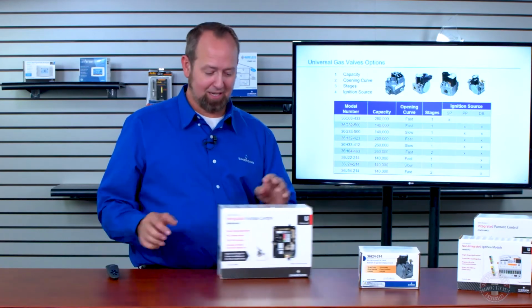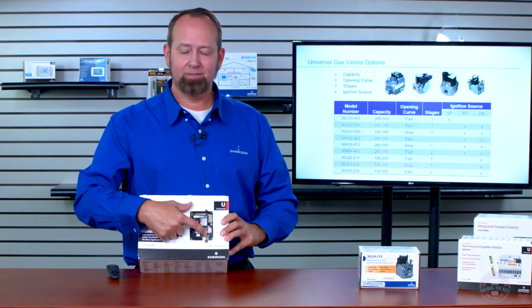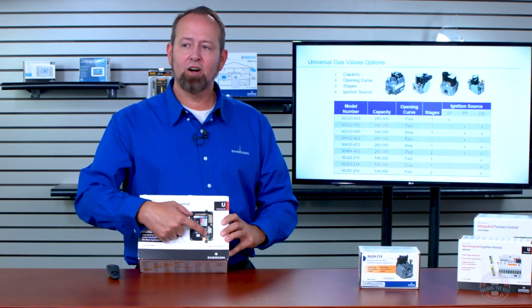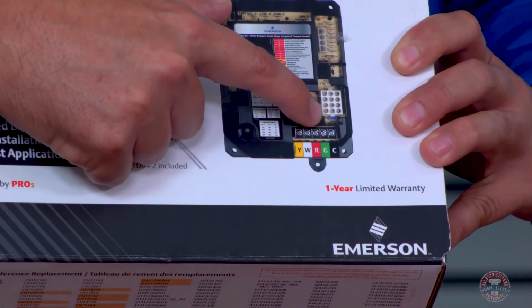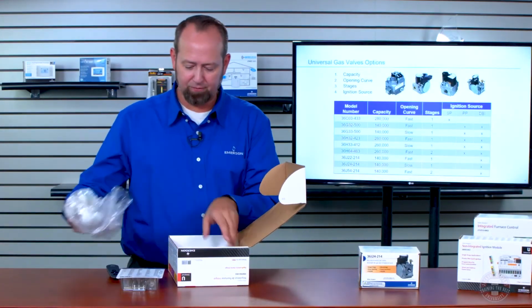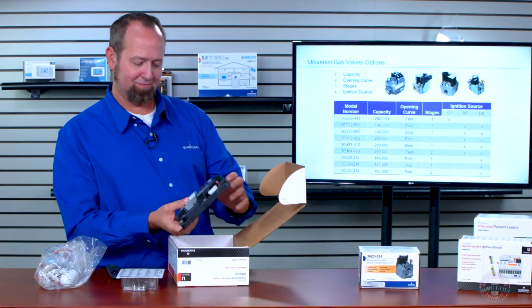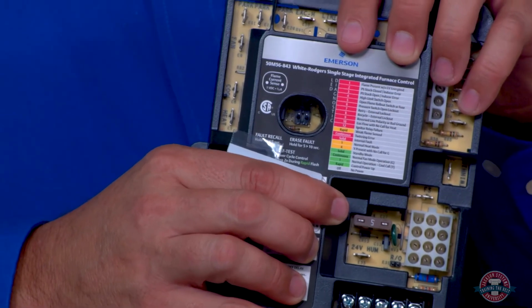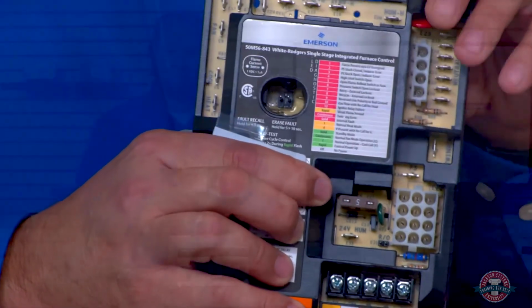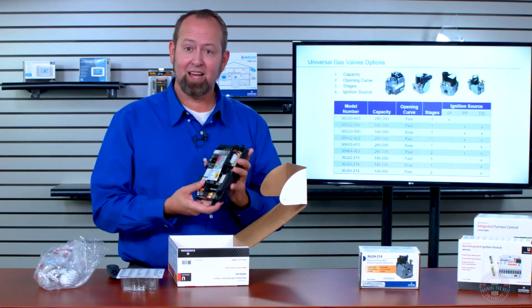Good question, Stephen. Again, and I don't know if I need to pull this out or not, but on all of the control boards, there are 3 amp fuses. I believe a few of them would have a larger capacity. I don't know if you can see that or not. Let me go ahead and pull it out real quick. It's kind of hard to see. Do have a 5 amp fuse, but most of them, I should say, actually, here we got the one with the 5. This one has a 5 amp fuse. What I was going to say is all of our boards are fused. So yes, to your question, there are fuses on all of the boards protecting that low voltage circuit.